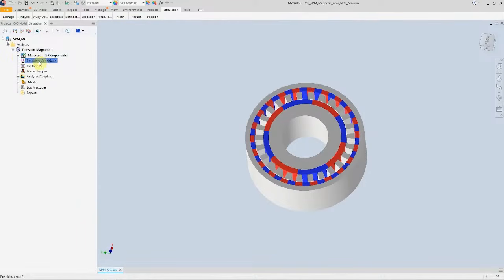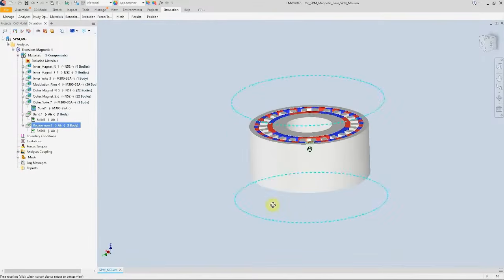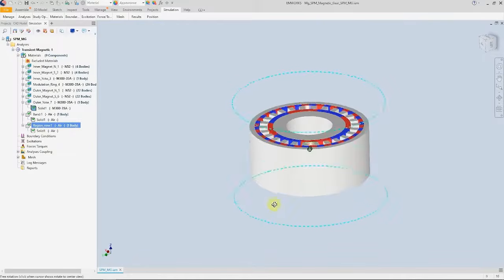About the boundary condition, you can select normal flux or tangential flux if you have any special circumstances. But for a 3D simulation without periodic boundaries, you don't need to set boundary conditions. The outer air will be the biggest part that will be meshed and solved.